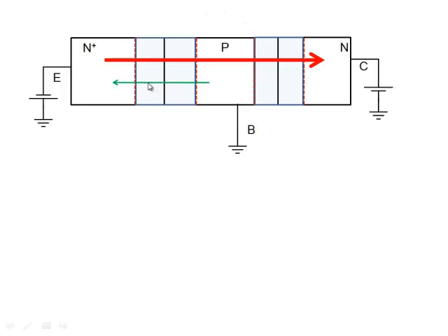So if you want to simplify, if the emitter-base junction is forward biased and collector-base junction is reverse biased, two dominant current components are there. One is the red one here, electrons going all the way here, and then there is a smaller component of holes. There are other currents, as I said, holes also flow from N to P, but they're negligible. It's a reverse bias junction, so you can neglect it.